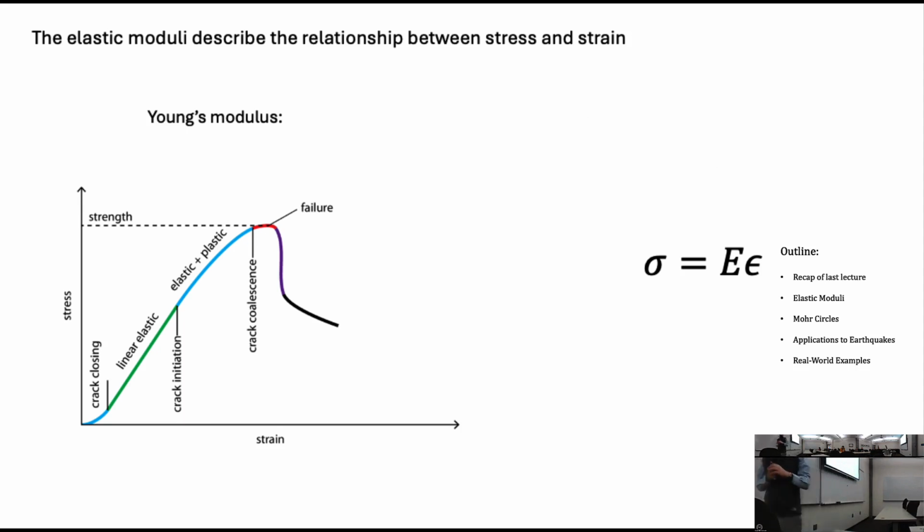The Young's modulus is usually considered the first modulus we go to. It just seems intuitive to geophysicists and petrophysicists to go to Young's modulus. And you can think of it as just the stiffness of the rock. So if you put a lot of stress on a rock and you get a lot of strain, then that's a low Young's modulus. And if you put a lot of stress on it and hardly get any strain, it's a very stiff rock, a high Young's modulus. This is just a concept to describe the rock. It's a property of the rock which shows essentially stiffness. It shows the relation between axial strain and axial stress.